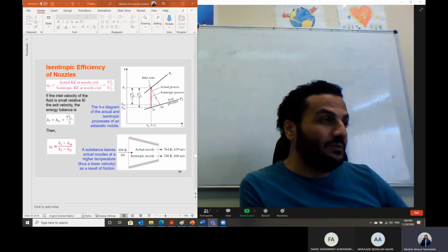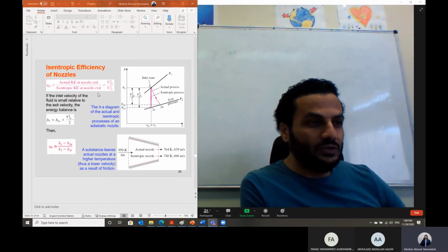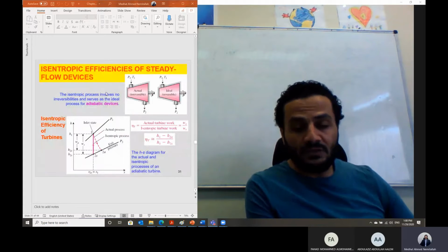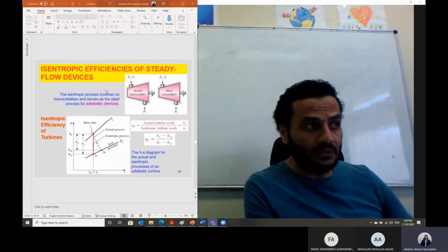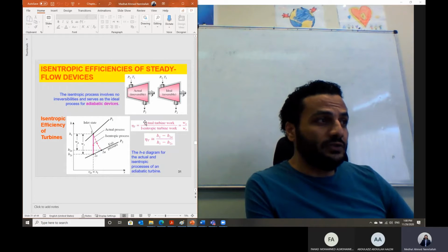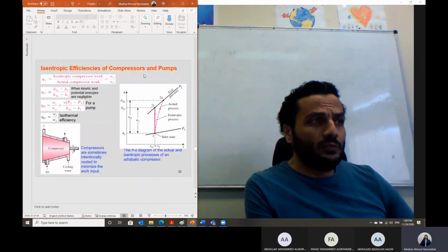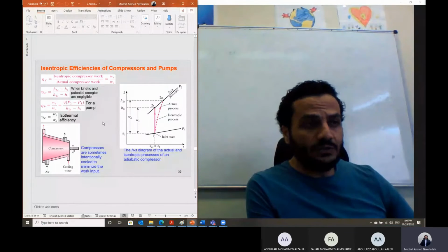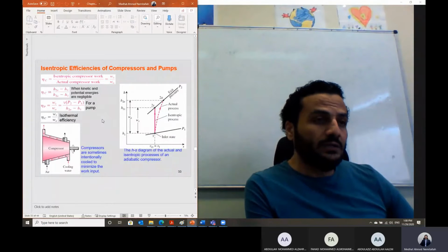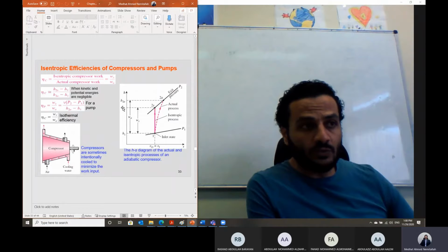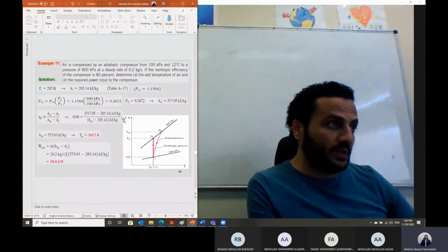Inshallah, today I will end up with the topic isentropic efficiency. We talk about isentropic efficiency for turbine. We said this performance parameter applies to the adiabatic steady flow device for turbine. We have learned how to calculate the isentropic efficiency for turbine. Then we move to the case of compressor or pump, and we learned how to calculate the isentropic efficiency for compressor or pump. In any case, it is a ratio between the actual work divided by the reversible or the isentropic work in this case.